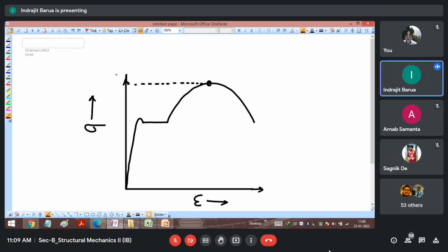Okay, great. So we know that this is the yield point. This is the point up to which we will be taking our material when we use it for the design, for our actual use. But this is the maximum which it can take. There is some concept of shape factor, on which we see how much it goes into the plastic zone, but you will be studying that in design.